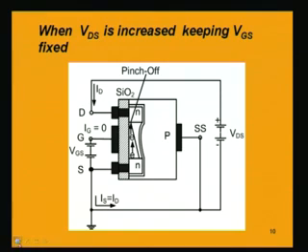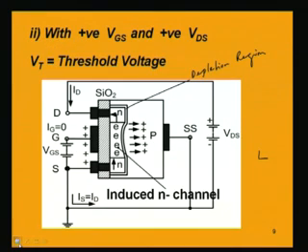Now, before that, one important point is that the name of this device is field effect transistor, FET. Where that name originates from also has to be understood from this operation, because now we see that the VGS, which is a positive voltage, when it is applied, there will be accumulation of positive charges on this side as is shown here.